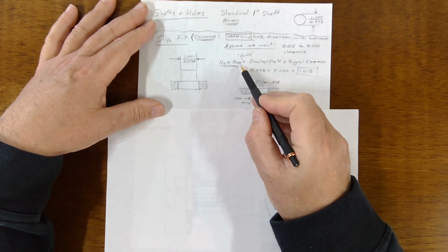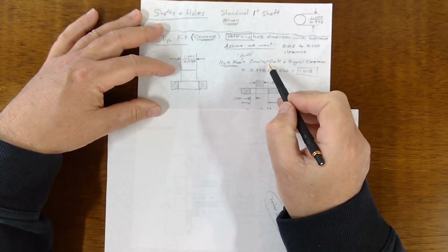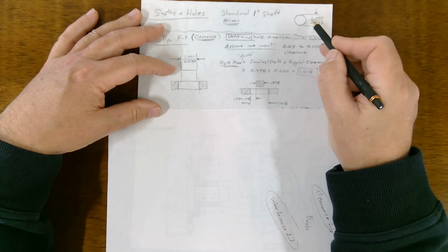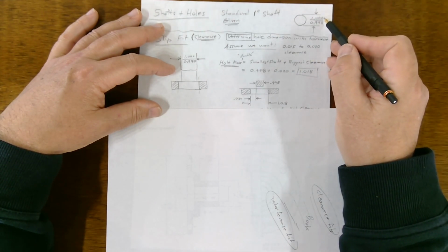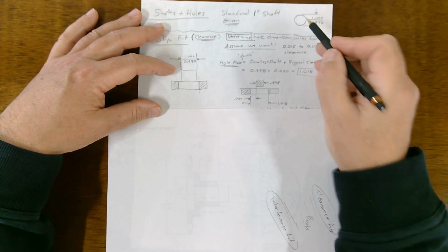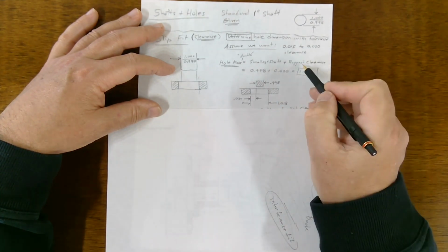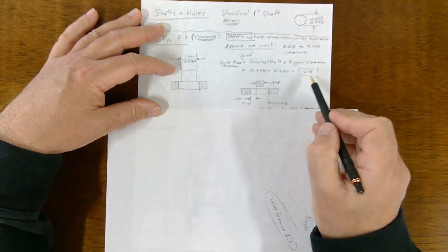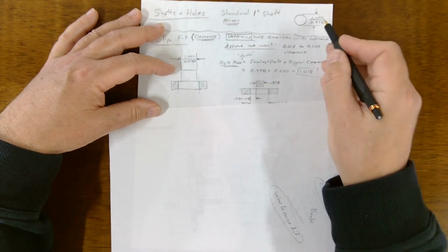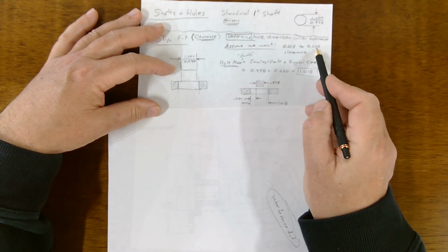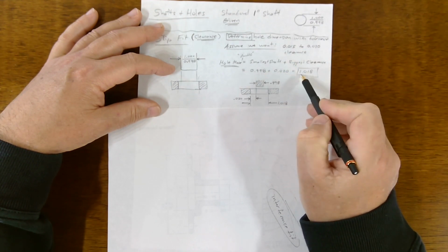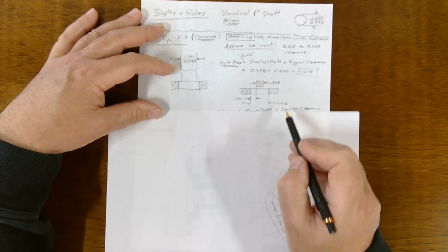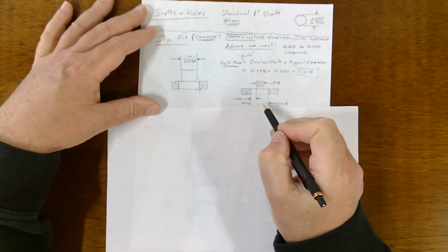So the biggest this hole can be, okay, think about it this way. You've got a bin full of these shafts, and you just pick one, and it's going to be somewhere in this range, but you don't know where in this range. So let's say you pick the smallest shaft, okay? And then you pick the biggest clearance. That's the condition for the largest hole. So the smallest shaft is 0.998 and the biggest clearance is 0.20, right? So add those together, you get 1.18. That's the biggest the hole can be allowed to be, right? And that's the formula, so just use the formula.